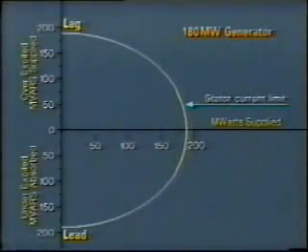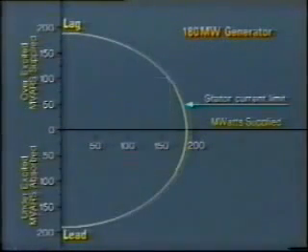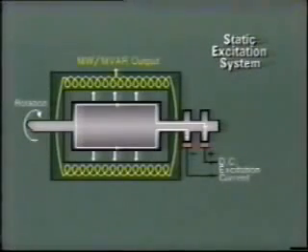This curve shows us the limitation of MVA due to current in the stator. For example, at this megavar loading, we can only produce this amount of megawatts to stay within the machine's capability. Clearly, in order to keep within the MVA rating, we must reduce megawatt output if we wish to produce a large output of vars on the generator. However, there are other limits to observe in generator operation.